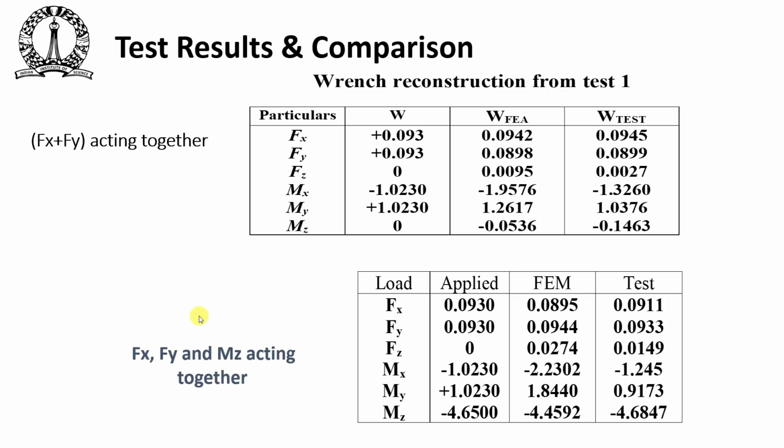Once we have this proof of concept that we can indeed measure Fx, Fy and Mz more sensitively, then we form that H matrix, again using some calibration. Then we find the inverse of the H matrix, okay, and then we do some real tests.